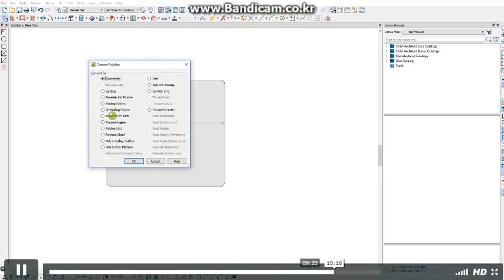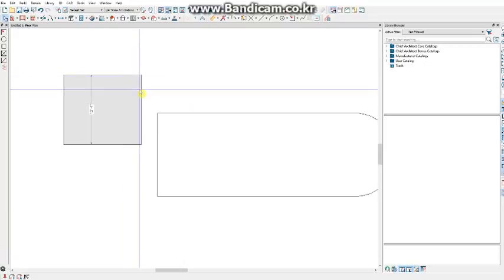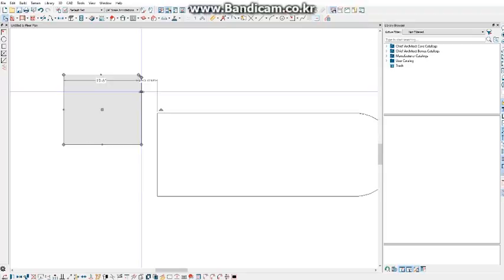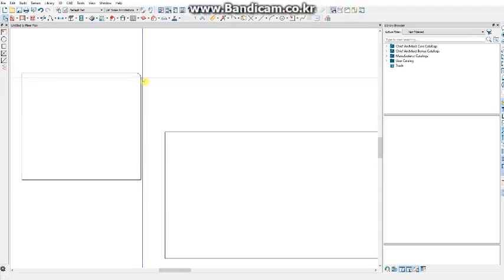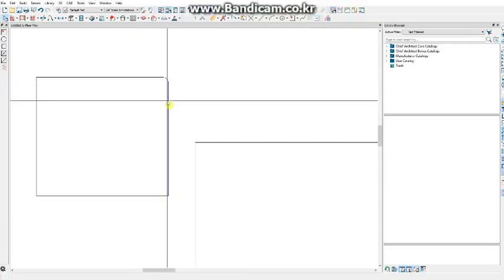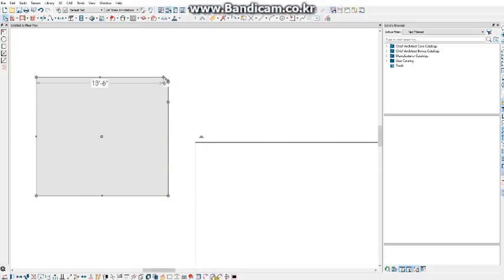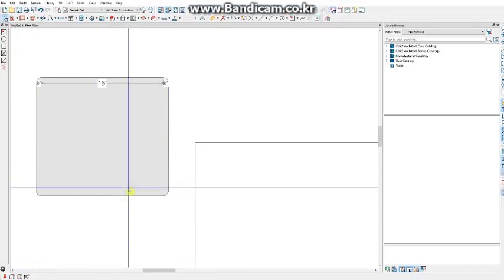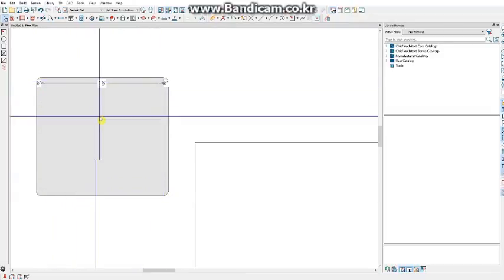That will round off the corner to an exact 6-inch dimension. If I click on that line, click on the Fillet tool, and then click on the Fillet All Corners tool, it will fillet all of the corners of that polyline.